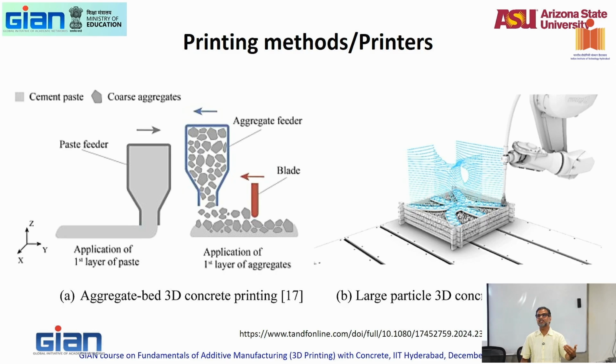Even if you can take a giant heater and put it next to concrete to make it set, it will give you lots of other problems as you go through. So you really don't have that option. You need to make the material itself do that process. So you have to control your hydration. That's what we will spend a good amount of time on, probably tomorrow: how do you control the early age property. So that's pretty much what it is.